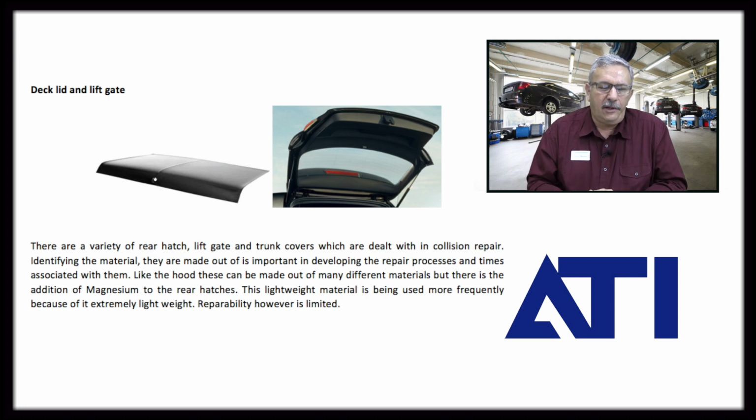And that's one thing that we will talk about in future sessions is knowing what the heat requirements are for the different types of steel that you're working on, because it can significantly change how the part is repaired because the metal on a high-strength steel part, it's thinner, it's got carbon, that makes it high-strength steel.